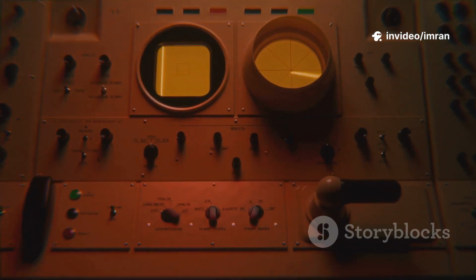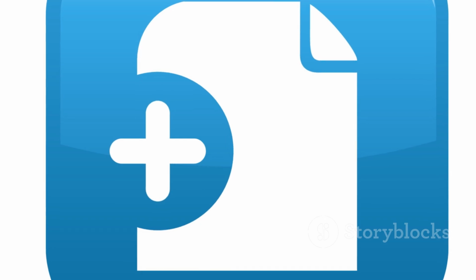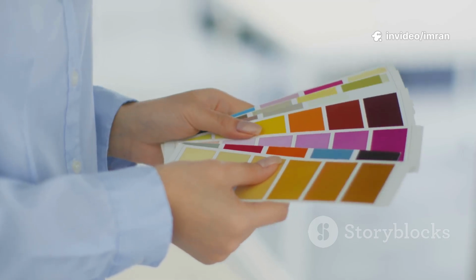Let's put the Layer Properties Manager into practice. The first step, set up the layers you'll need. Open the Layer Properties Manager and create layers for a simple architectural plan. Create 3 layers: walls, doors, and windows. Assign a distinct color to each layer.